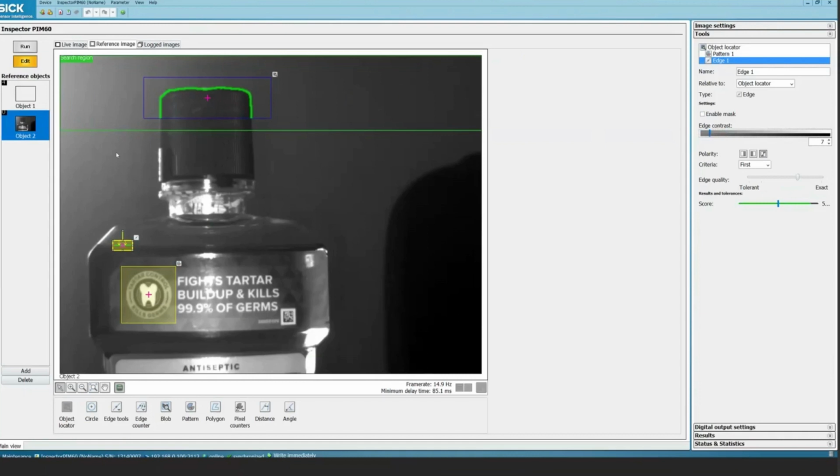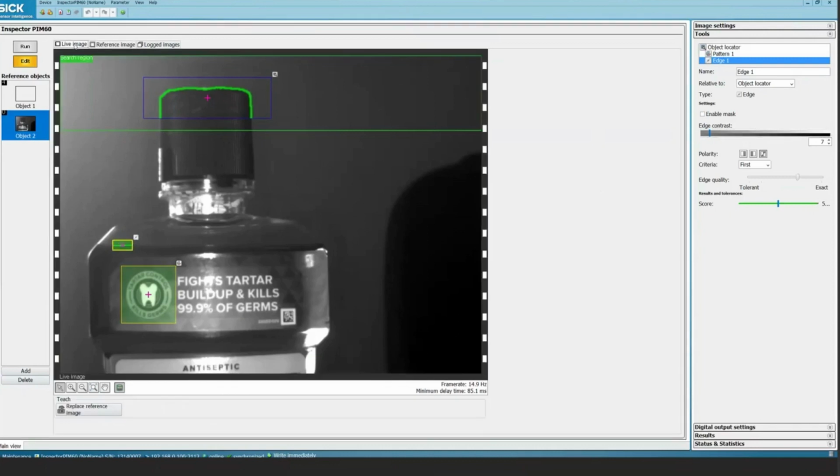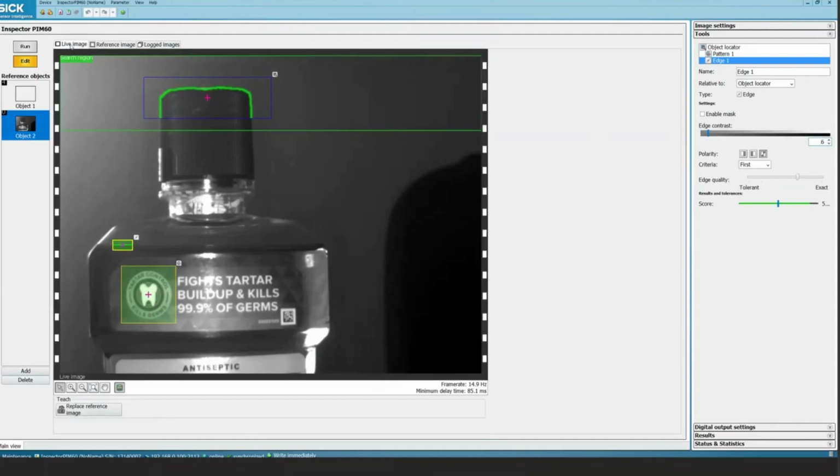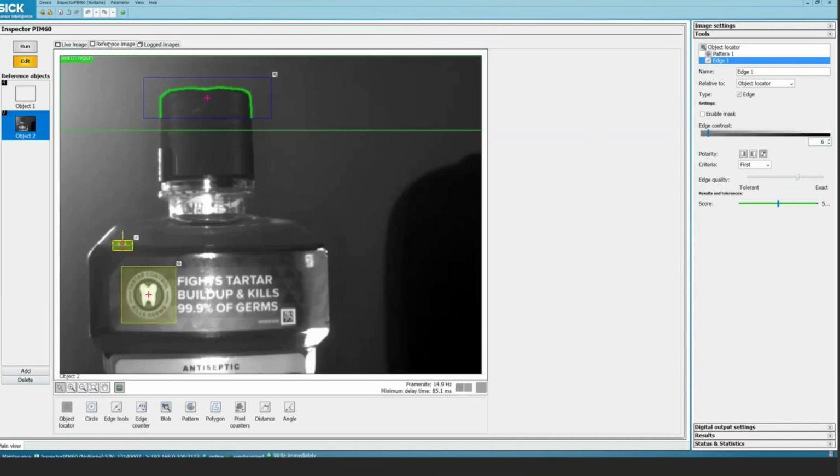Just to make sure that it's good, it's stable, we'll go to the live image to see if it's green and stable. And yes, it is. So, oh no, but it just saw a red one. So maybe we can reduce it further down to just have an optimized image. Okay, now it looks good. So fill level is done.